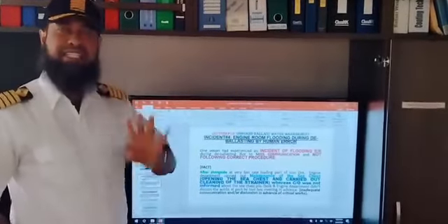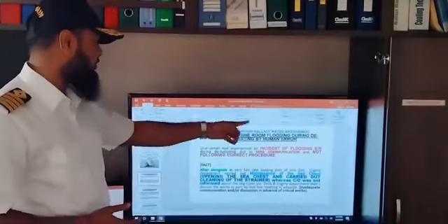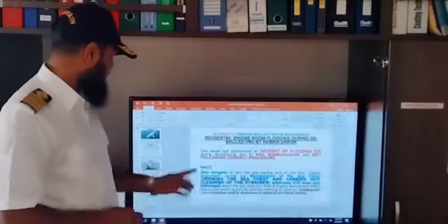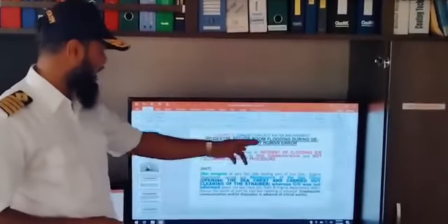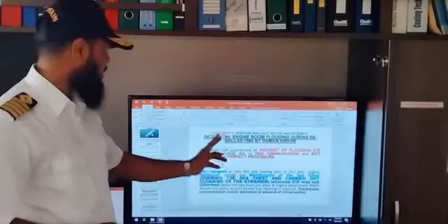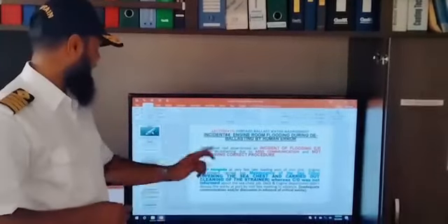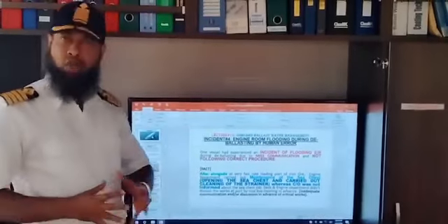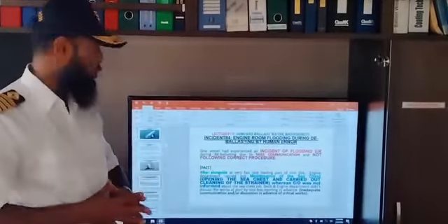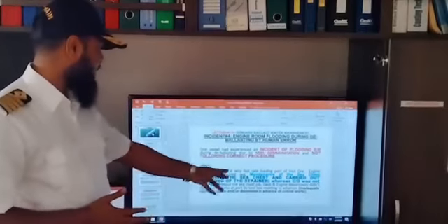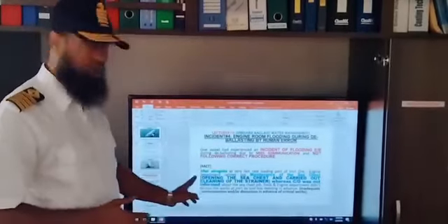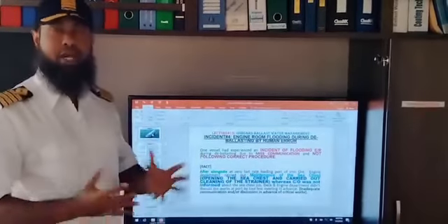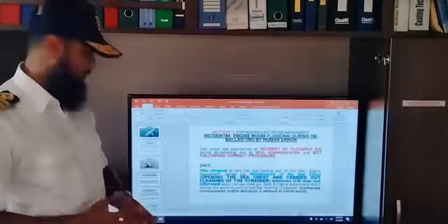And now number 4 incident we can share, that is engine room flooding due to deballasting and human error. For example, one vessel experienced an incident of flooding the engine room during deballasting due to miscommunication and not following the correct procedure. In fact, after being alongside in a very fast loading port, the engine department carried out maintenance of the sea chest, opening the sea chest and cleaning the strainer, while the chief officer was unaware of this fact.